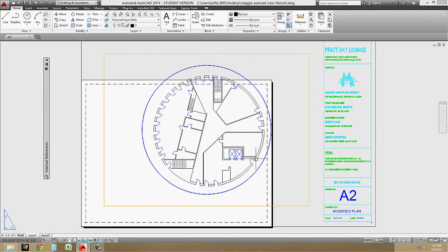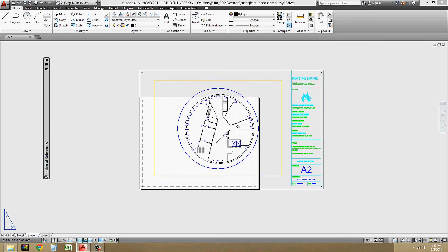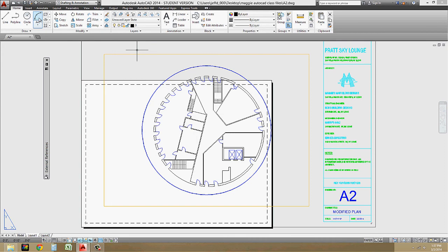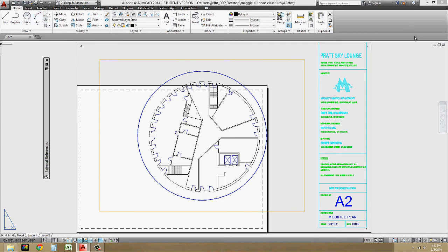If you need to change the scale on it, that's fine. Basically, you should kind of keep the same scale from 1 to 2, but if it's not going to work, then that's fine to just change the scale if you need to. Okay, so that's my sheet A2. Just do a zoom extents, because that's a nice habit to get into when you leave your file. And I'm going to hit save.